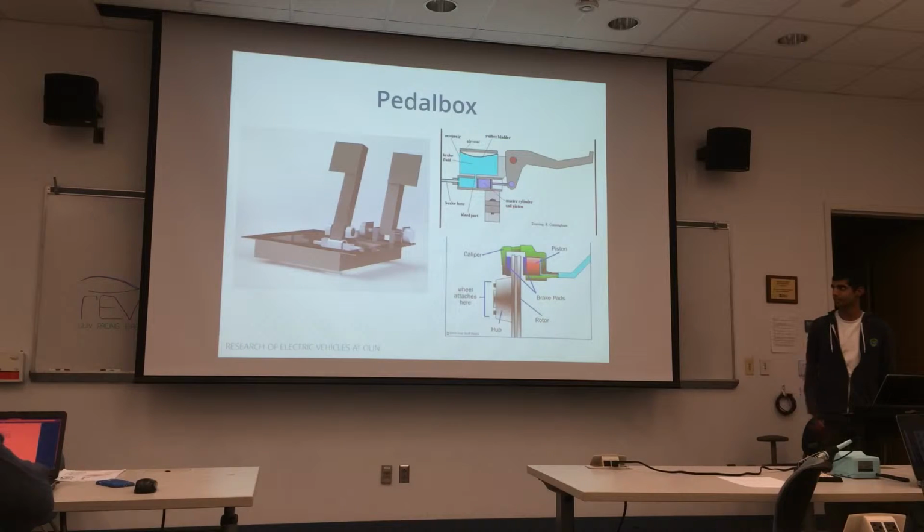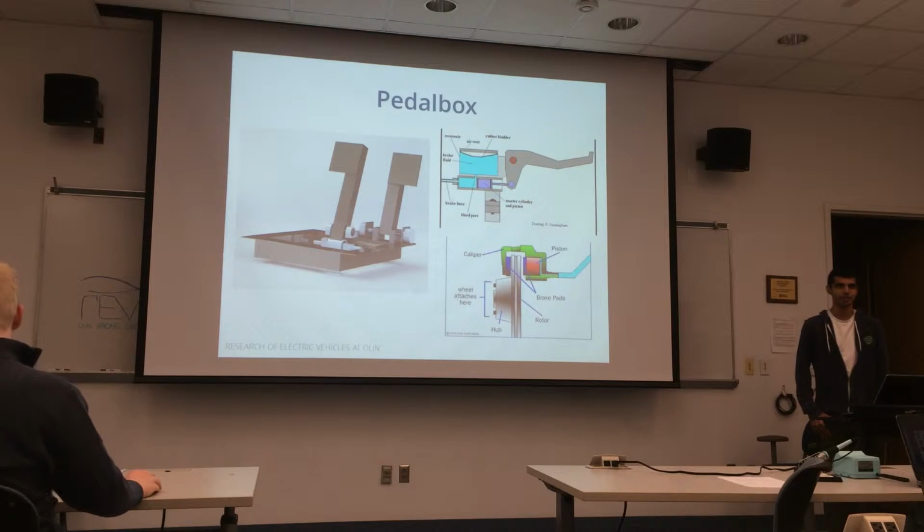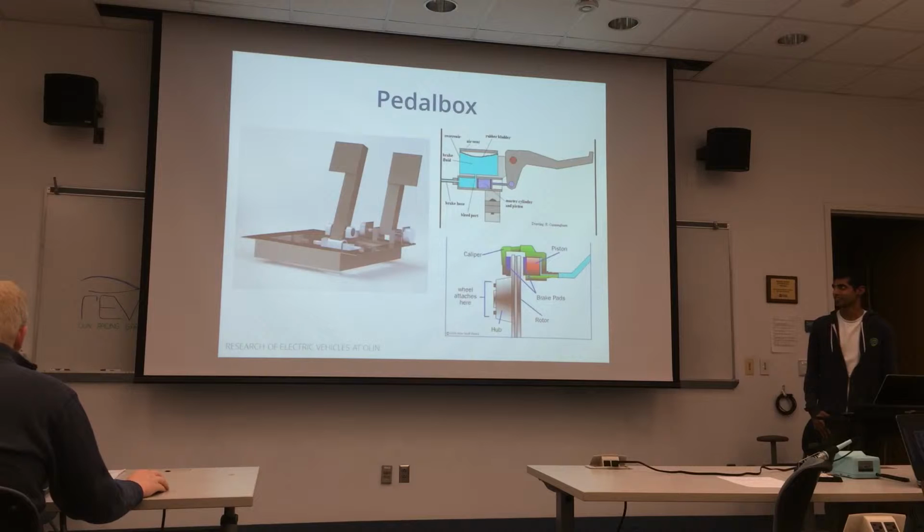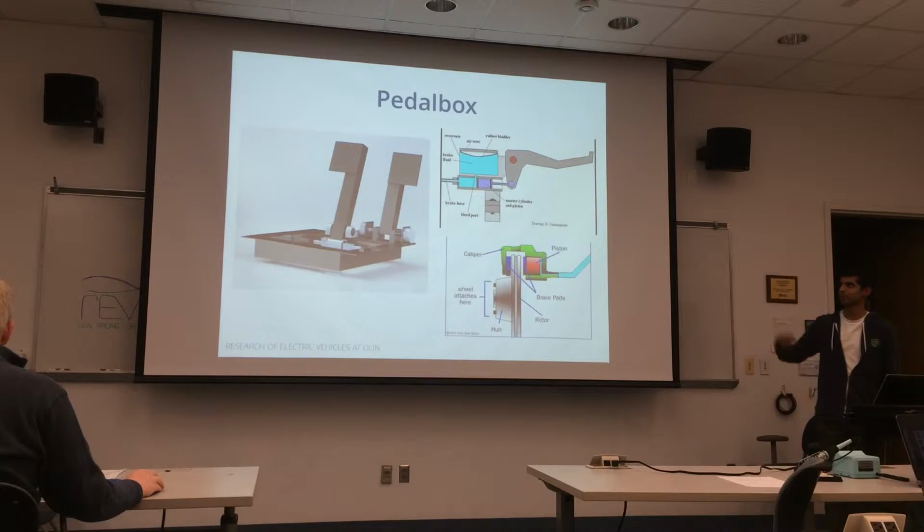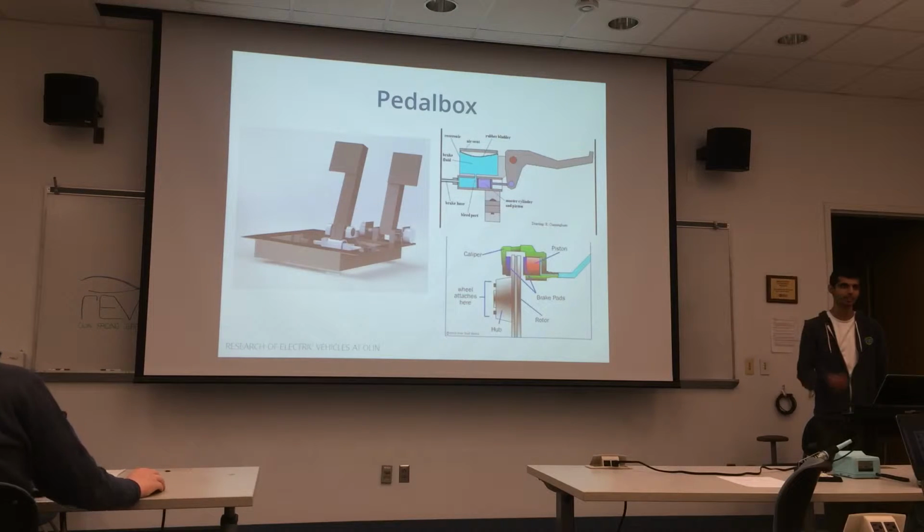And then on the other side, we have our brake pedal. And this is just a really brief picture of how brakes work, in case you guys are wondering. Basically, when you push down the pedal, you're compressing some sort of brake fluid in the master cylinder, that thing up in the top, and that pressure gets drawn through some brake lines and comes down into the brake calipers. And these just sort of wrap around brake discs, which are giant spinning discs that spin with your wheels. When you apply pressure from pushing down on the pedals, it compresses and the friction slows down your car. So that's the pedal box. It's super important for everything.